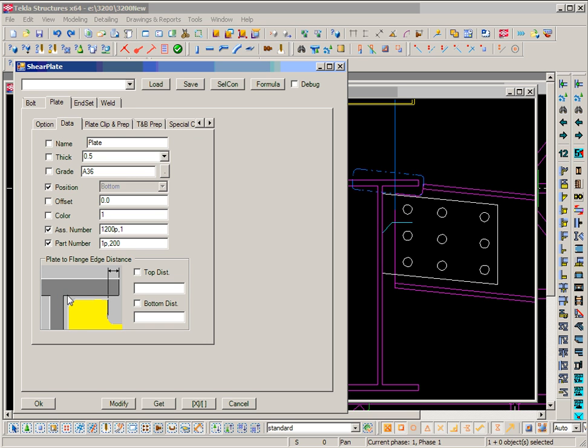So if you want it to touch the top girder plate, then you need to give a minus number. Like if you want it to be 4 inches, then you need to give a -4, and same as the bottom one.